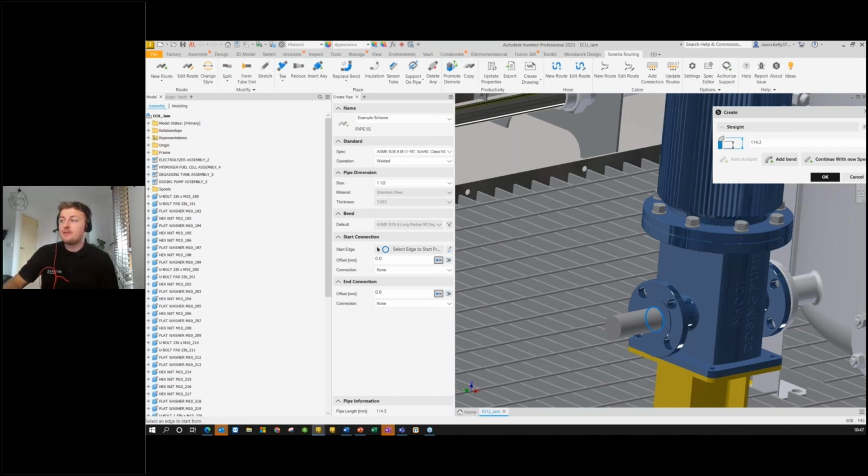So what we're doing at the minute is just creating a bit of pipe, but that pipe has a size to it. I'm going to drop this down and change that size to a 2-inch pipe. What the spec is going to do is allow us to configure any fixtures and fittings that are going to sync with that particular size of pipe, or that particular instance of pipe. So the first thing the spec is going to pick up is the connection.